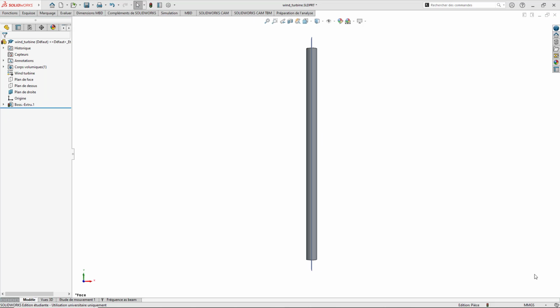One team of students, the team of Florian Desneux and Ayoub Kachaf, had also checked their results using SolidWorks. So what I've done here is take their file and adapt it so that it would correspond to the wind turbine that we have studied in this video presentation. The advantage of using SolidWorks is of course that you can check the results, but that you can also take into account the shear effects. We'll see here that in fact they can be neglected because we obtain very similar results to the ones that were obtained using the finite element method.